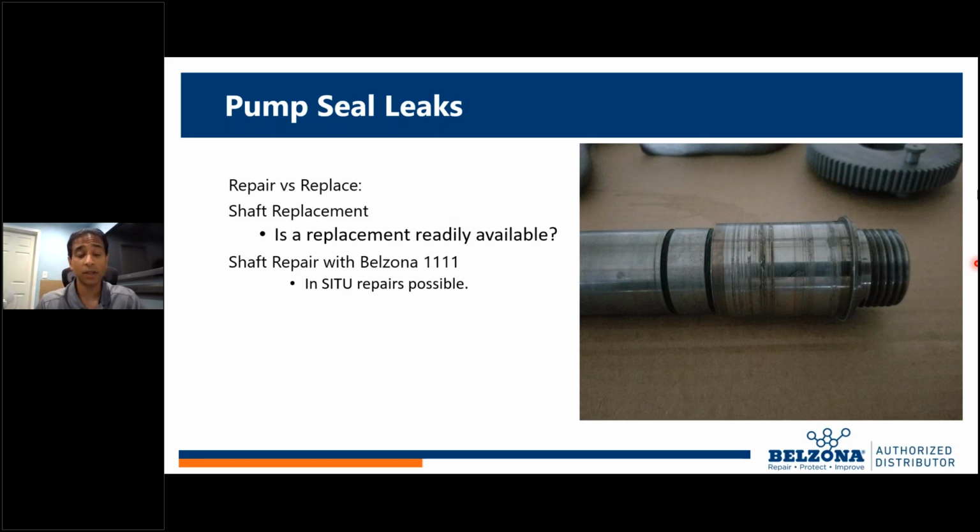And the fact of the matter is, whether you've put in a new motor, you swapped out the pump, maybe the pump base is going bad, maybe the motor base is going bad, maybe you swapped out some piping, all of these variables can lead to little micro vibrations within the pump. Well, micro vibrations start eating slowly at your pump shaft as it rides the seal. When it starts eating away enough and it's flexed enough, guess what happens? The process fluid inside the pump is going to start sneaking its way outside the pump, and now you've got